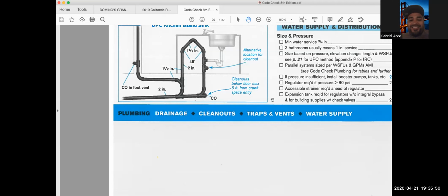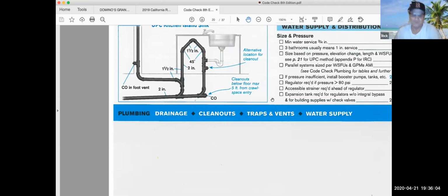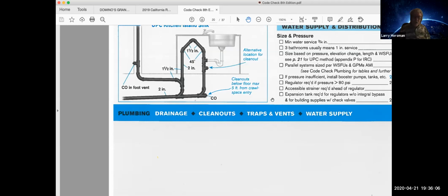Yeah, right. So if you see the red on the right and the blue on the left, either they've got the pipe in backwards, or they've put the hot water in the wrong place. So according to the plumbing code, the hot water should be on the left and the cold water's on the right. And that's a safety feature.